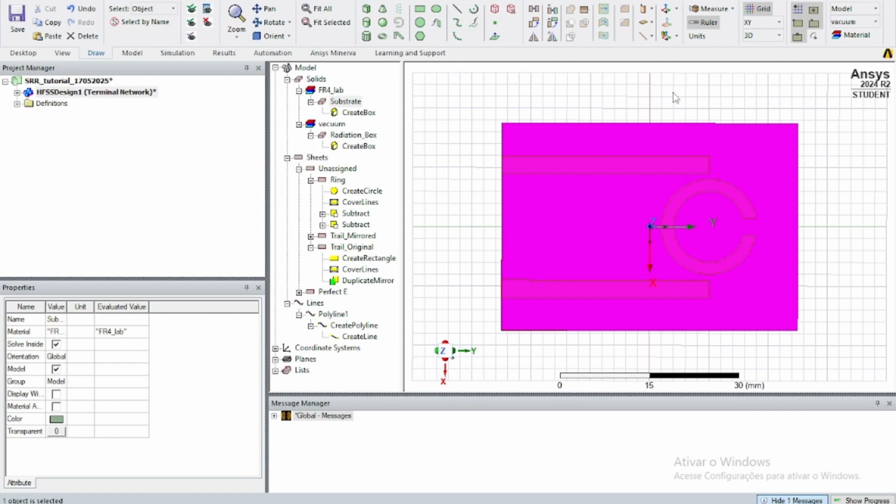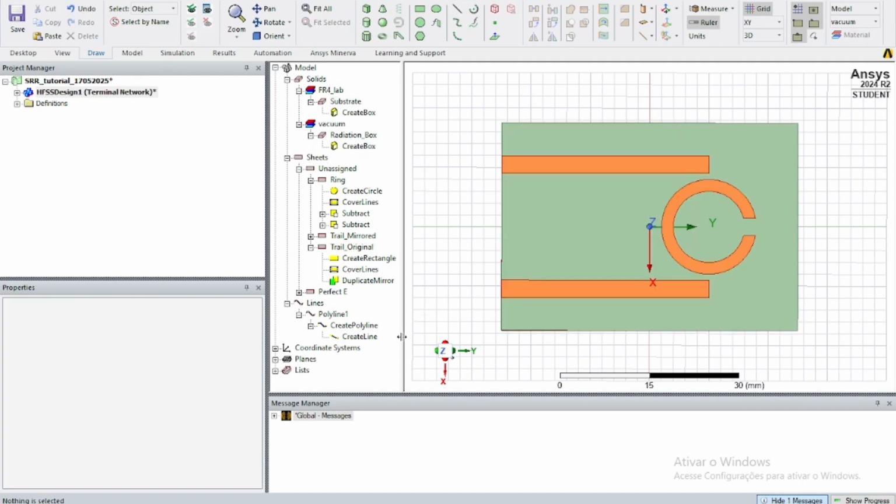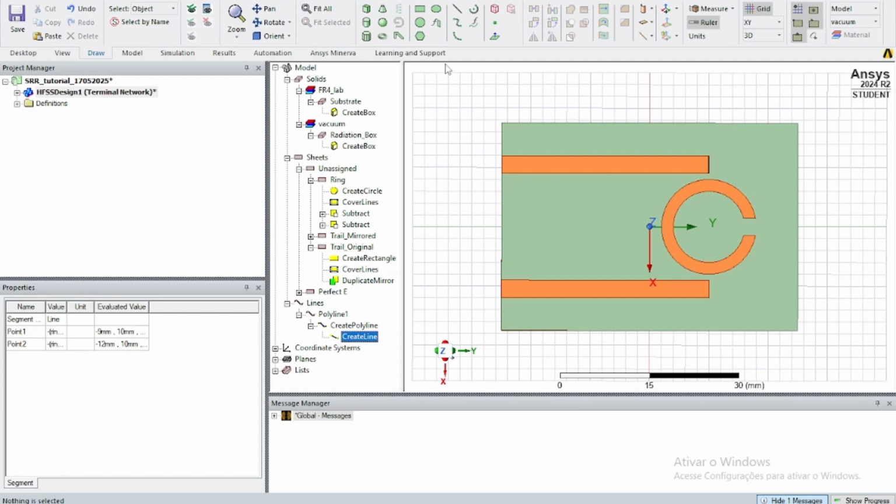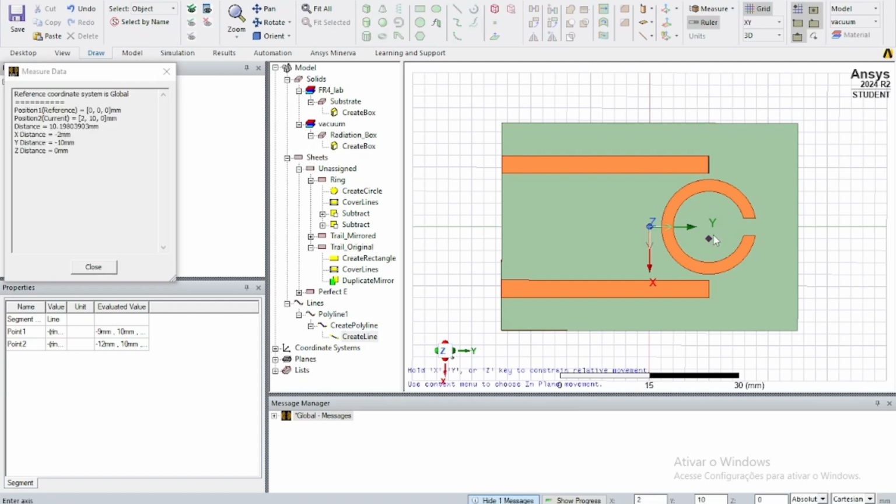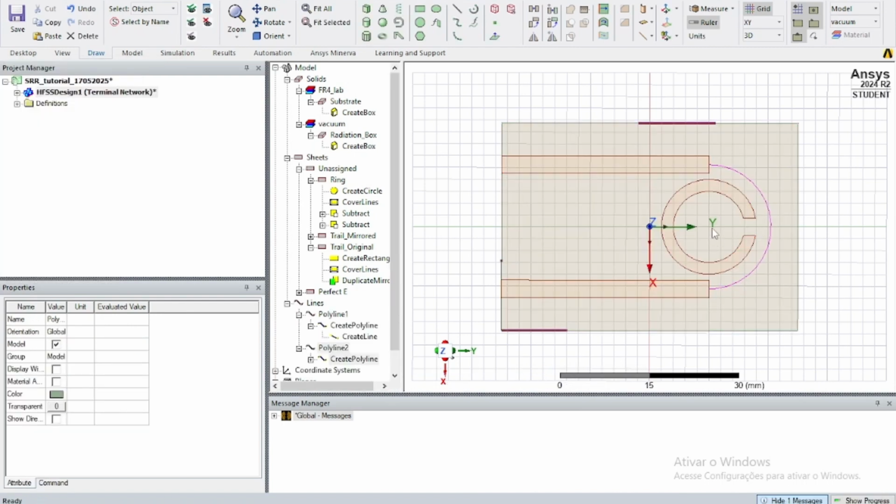Okay. Yes, so we have the line here, and now we create the arc by selecting this one, draw center point arc. So it's basically this, and then this. So click on the center, click on the middle of this polyline, then click on the middle of this one, and you click again here, and then you end.